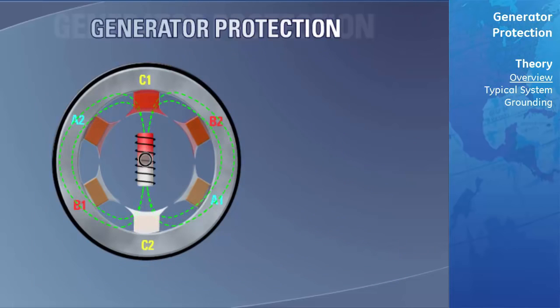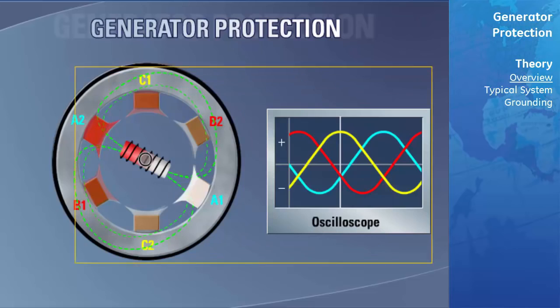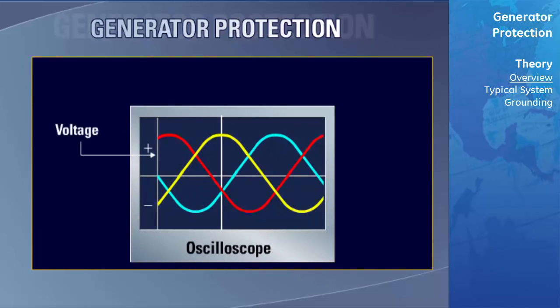If we plot a graph of the voltage which appears across each of our load resistors against time as the exciter rotates through one revolution, we will see the waveforms shown. As the exciter rotates, the voltage induced in each pair of stator windings will be displaced by 120 electrical degrees from the other two waveforms, corresponding to the physical angular position of the stator windings. The resulting output is the desired three sine waves of equal amplitude, but with a 120-degree phase shift between them as shown.